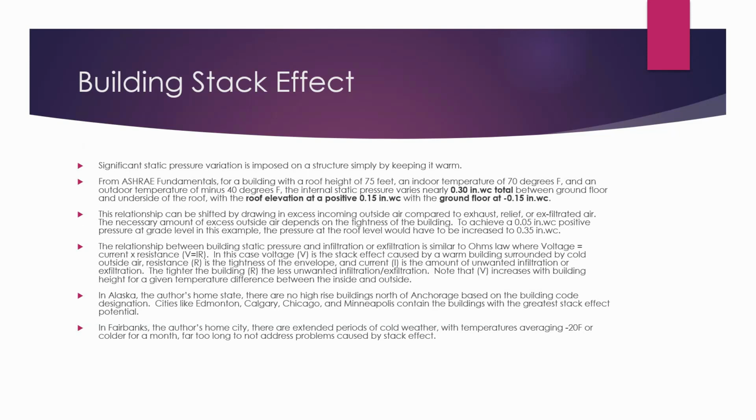The relationship between building static pressure and infiltration or exfiltration is similar to Ohm's law, where voltage equals current times resistance. If we're looking at this on the stack effect issue, in this case, voltage is caused by the warm building surrounded by cold outside air, or maybe we'd call that the potential.